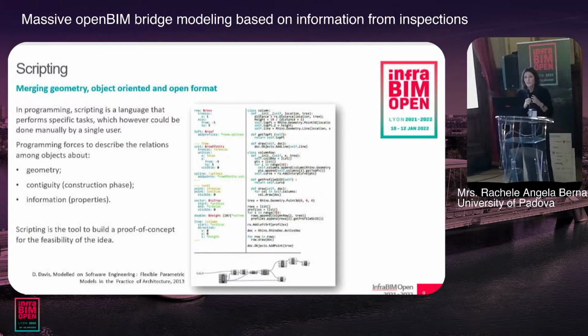So with the use of scripting and the VPL, we can clearly and definitely specify the relations, the geometry, and all these choices of the model itself, and so we can be apart from the specific software and just define all the structure of the BIM model that we want.